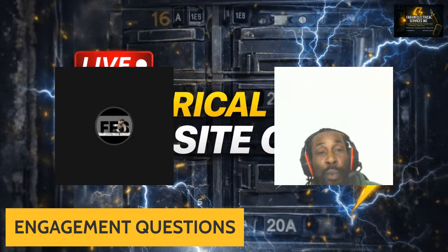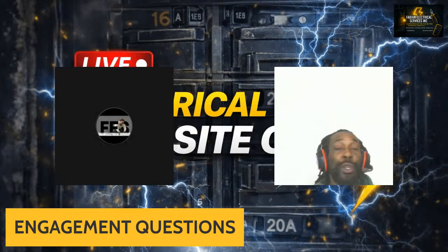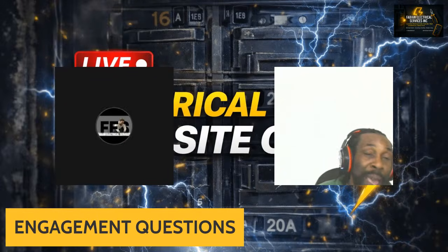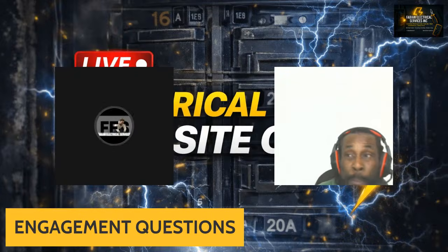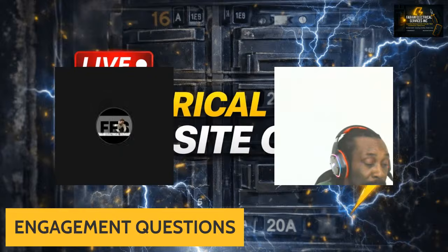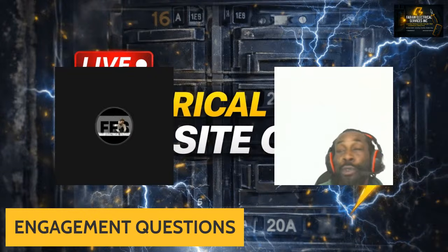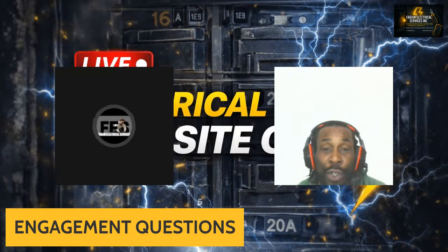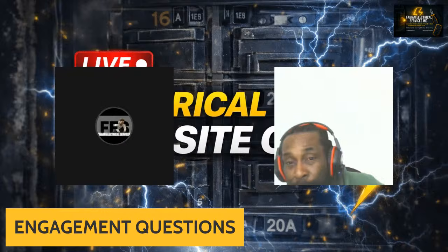When am I going to use this? Circuit breaker finders are used best for renovations. You're trying to find the circuit. When it comes to renovation, you know that there are going to be a lot of cables not labeled. People are going to move around circuits and so on. It's going to make your job a lot harder to find the actual circuit itself.